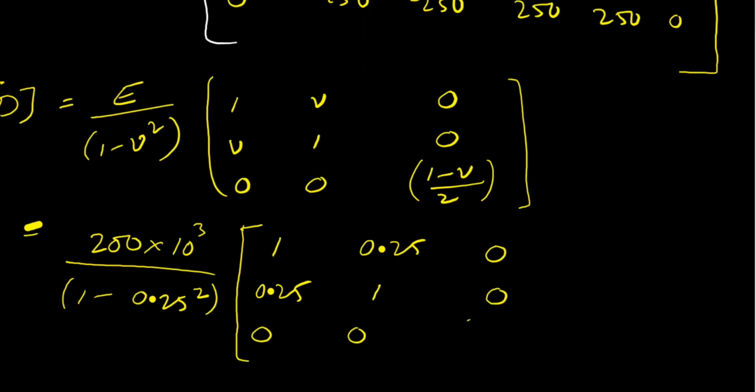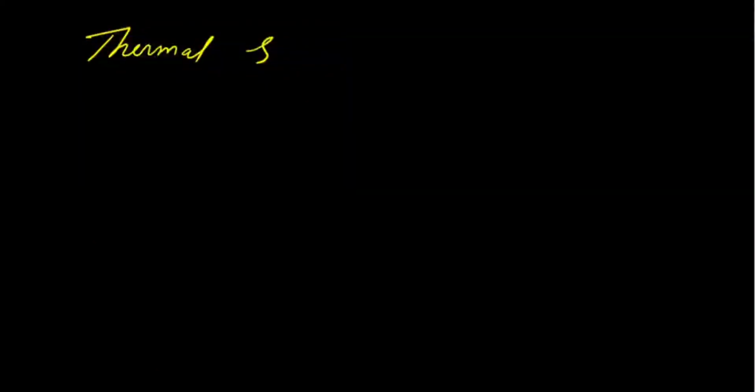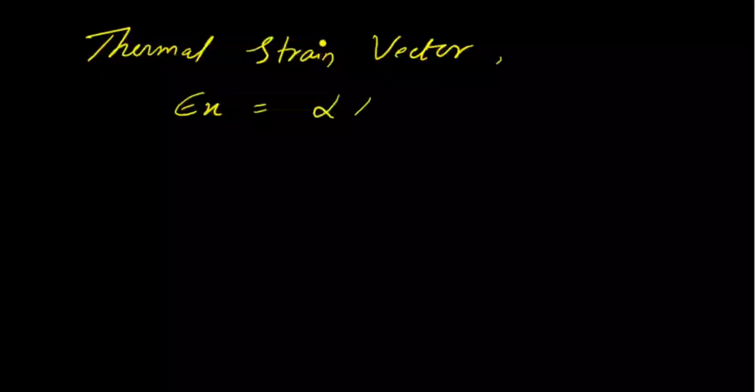Now we'll make the thermal strain vector, which means a load vector. Epsilon x is equal to alpha into change in temperature.